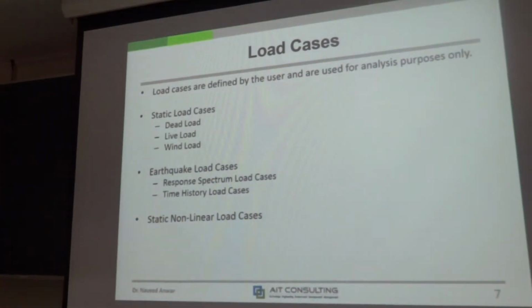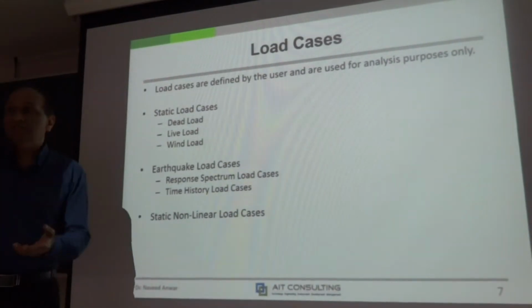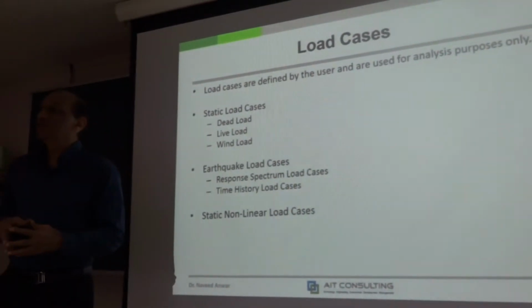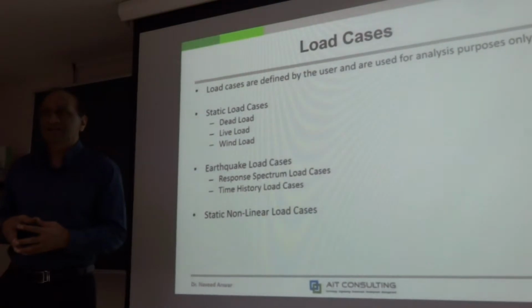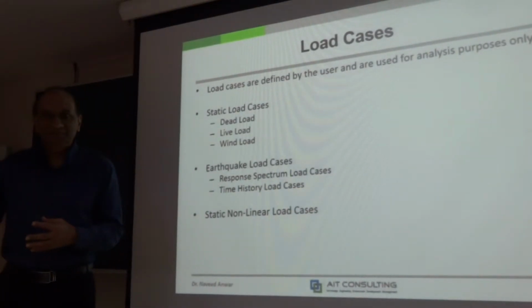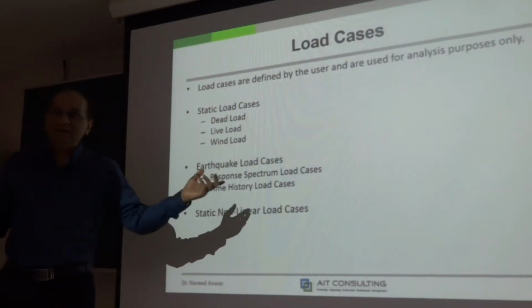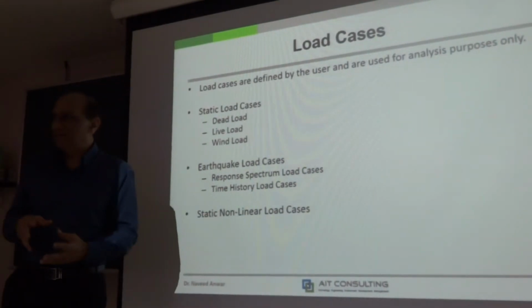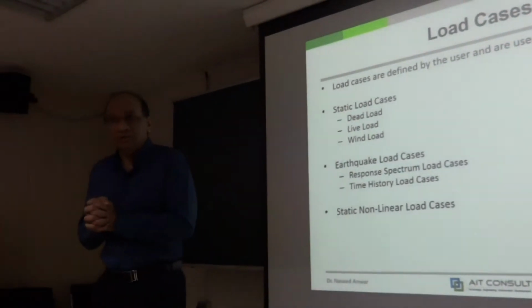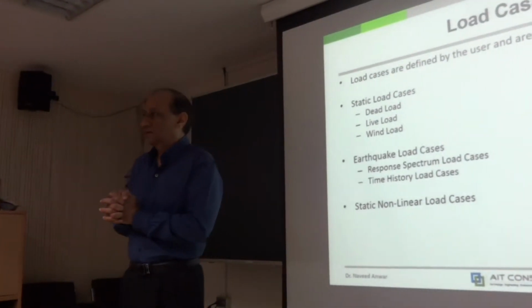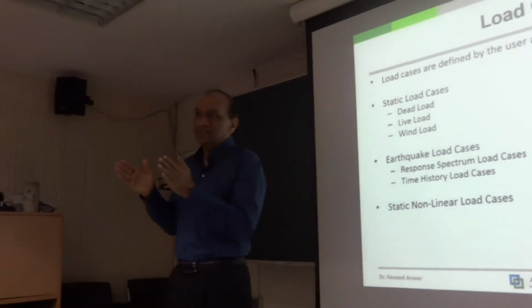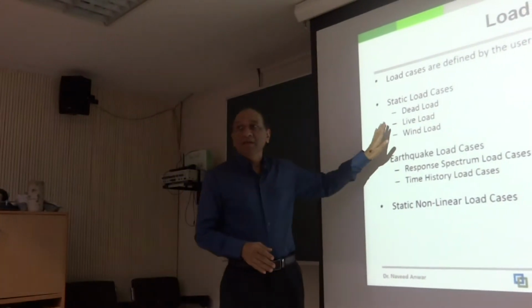Because dead load must be combined with, let's say, 36 wind directions, every 10-degree angle, and positive and negative. And if you have live load also, you also want to combine that. So if you really want to do it in detail, it cannot be done. So we have to say, okay, that's why design criteria is very important.